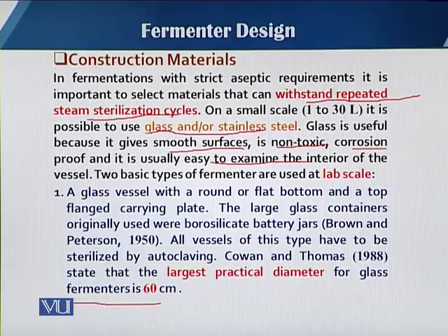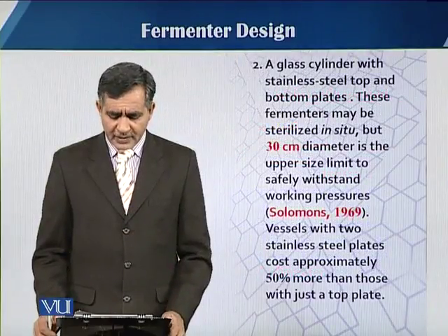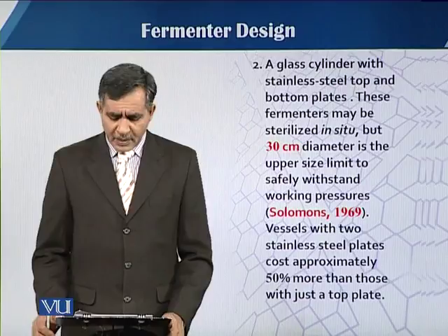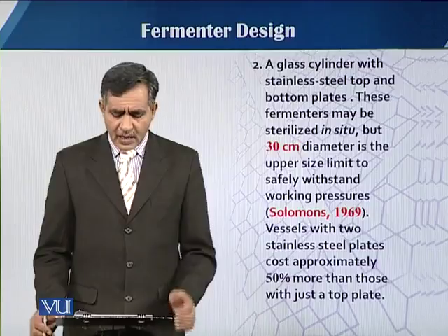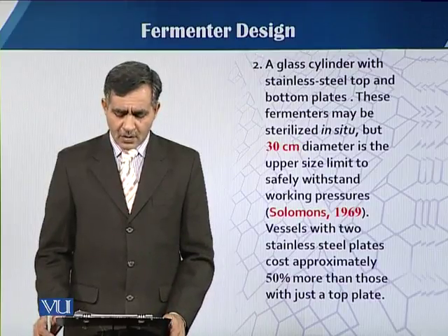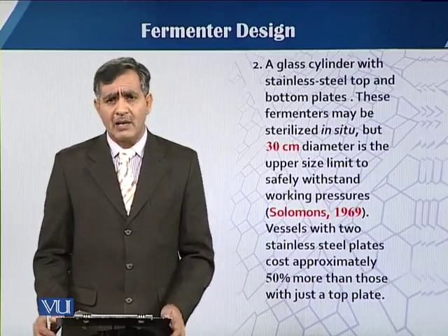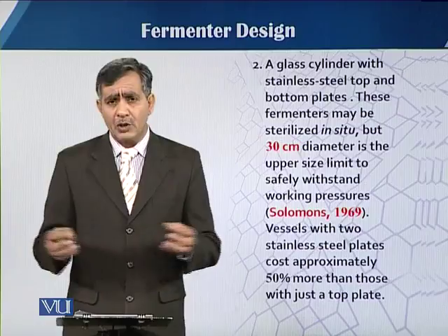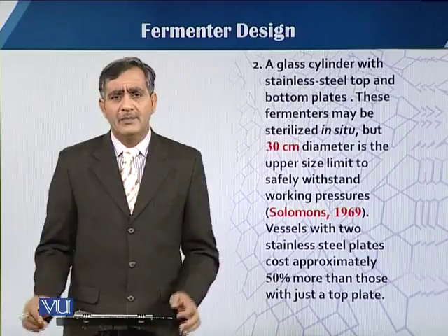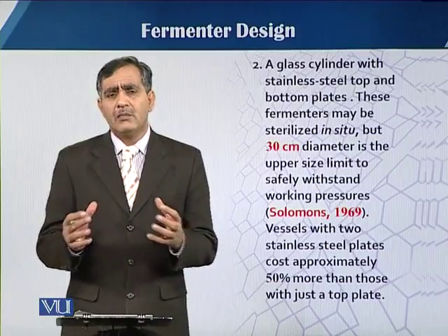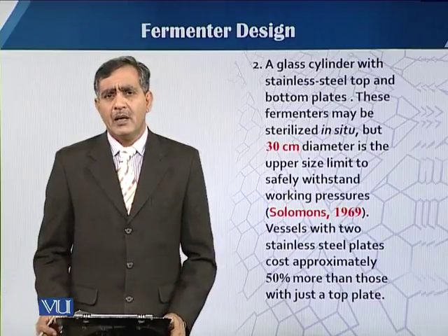But in the case of a glass cylinder with stainless steel top and bottom plates, these fermenters may be sterilized in situ, but 30 centimeter diameter is the upper size limit to safely withstand the working pressures during in situ sterilization, because then there is pressure, and sometimes there is a double jacketed wall, because we have to maintain the temperature by using steam.